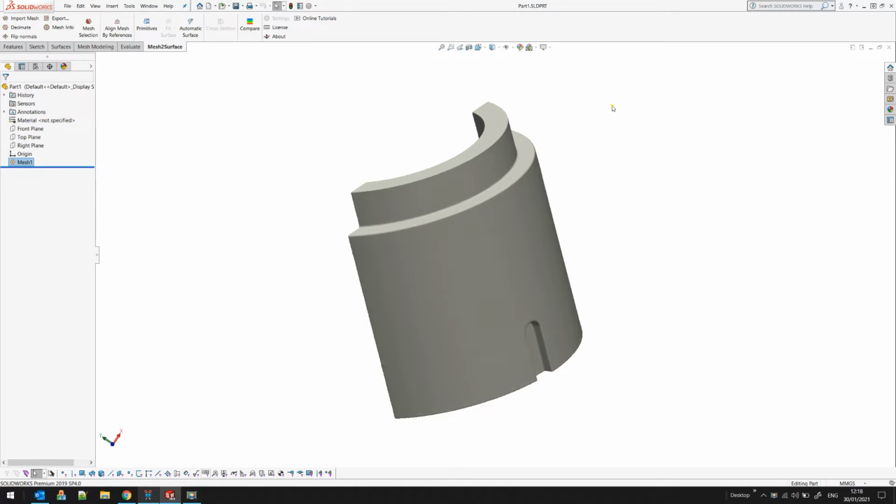This tutorial we will go through the mesh selection and what it is. For many reasons and for different tools, we need to get the part of the mesh that is needed and that we want to focus on, in order to define primitives, fit a surface, or just extract information only from a particular part of the mesh. Also, this approach can be used to remove some of the areas that are not currently needed, so the user can focus and work in a specific area.